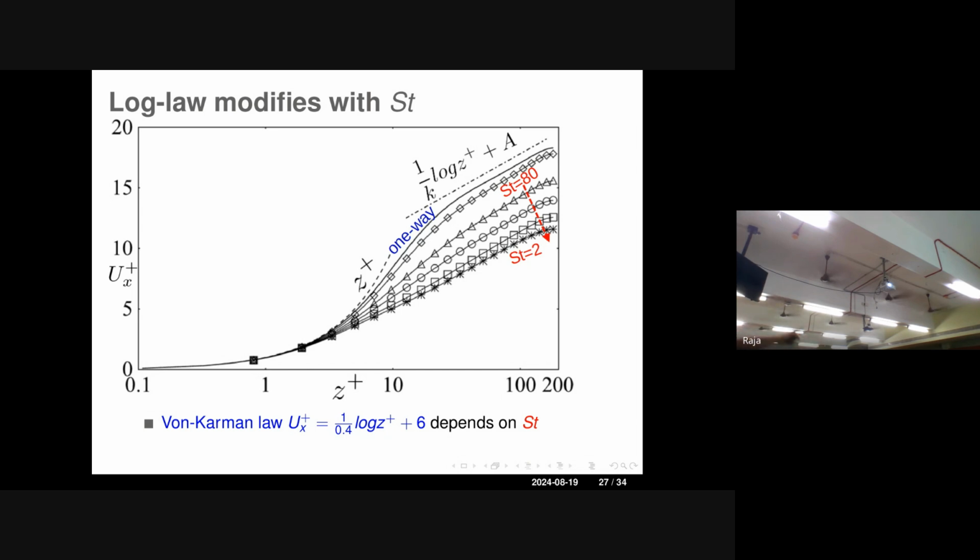It can be done, but the main challenge for turbulent flow simulations is not about that complexity. The complexity comes in whether we can really go with spectral accuracy, even in identifying the structures. Second order accuracy is completely useless for typical high speed and low speed streaks. So you will require spectral accuracy, or at least 6th order, 8th order accuracy schemes. Even to talk about Re tau 400, you require spectral accuracy, on which you require particles.